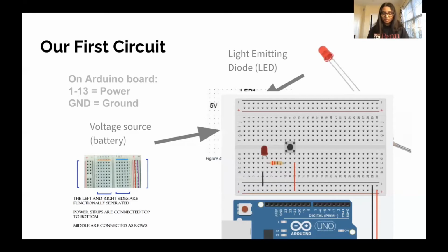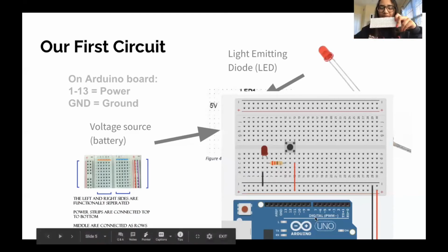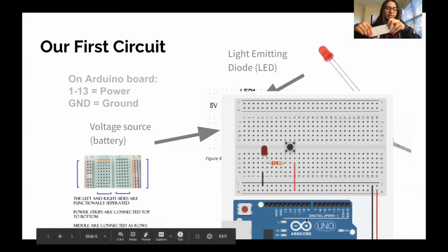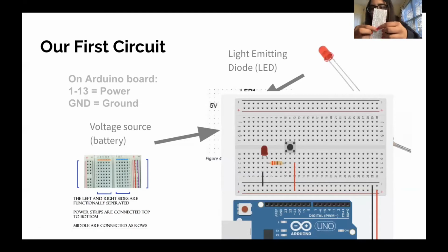Yeah. So the next part I want to introduce is a breadboard. It looks like this with a lot of holes, and mine is quite large, but usually they are pretty small, like the one in the picture. The anatomy of this is described in the diagram at the bottom left of this slide. In this, the far right and the far left columns are all connected with metal under the plastic.